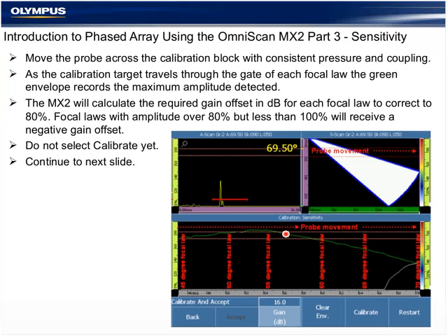So whether you understand what I just said or not, as a regular user of phased array, the working man's result of that is that I can complete this wizard with a wider sector scan or on a hole deeper than I would be able to without use of gain compensation.